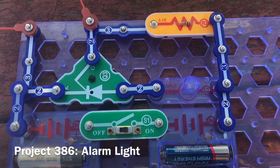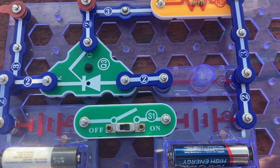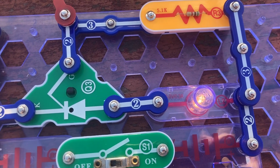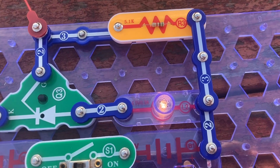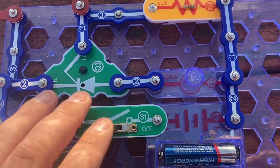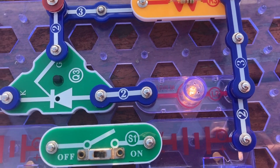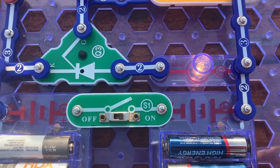This is an alarm light. It will use a visual signal instead of an audible one. I have the lamp, and when I disconnect the jumper wire, the lamp comes on. However, unlike other alarm circuits, reconnecting the jumper wire will not turn the alarm, or the light in this case, off. Instead, you have to turn off the slide switch and turn it back on again to reset the alarm. Because with the Q3 diode, the circuit remembers if there was a break in the connection.